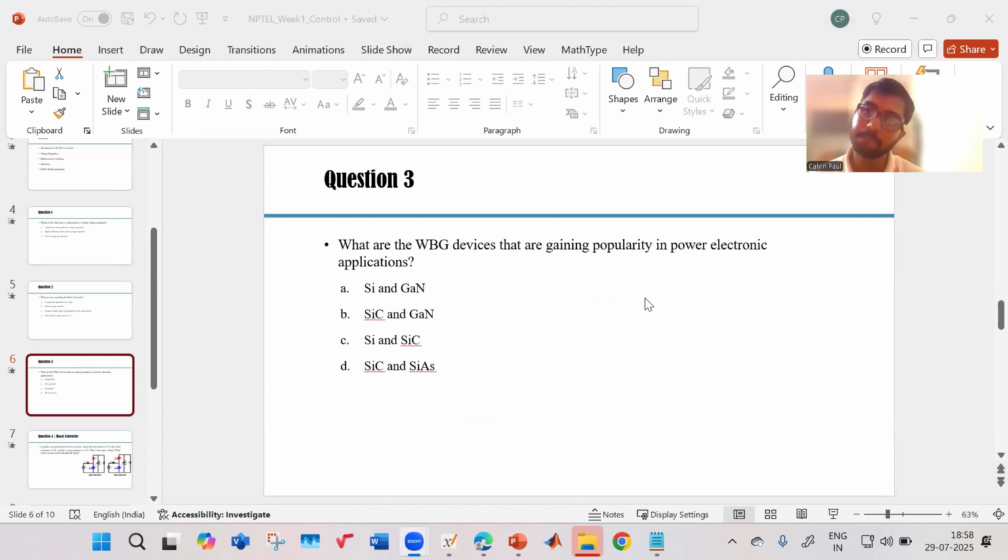If the switching frequency is high, then the amount of inductance and capacitance you require is less. When you derive those expressions for inductance and capacitance, you will see that the switching frequency is in the denominator. So if you increase the switching frequency, the size of your inductor and capacitor becomes smaller and you get a more compact power supply.